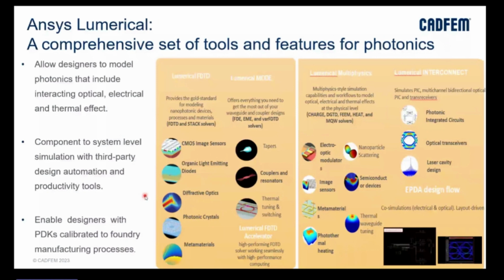The issue could be the complexity of the structure. If the structure is too complicated, for example metamaterials, some changes need to be made in terms of meshing or boundary conditions. That can make your simulation longer and more computationally expensive. So in that case we need high performance computing to simulate it effectively.